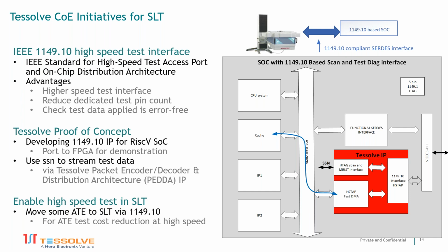Because the structural test they do on ATE is very, very expensive, because of the cost of that ATE equipment, and they measure test runs by the second. If they can shave half a second off the time they spend on the ATE, that saves them a lot of money. So they're always trying to do their fault coverage with fewer and fewer tests on the ATE.